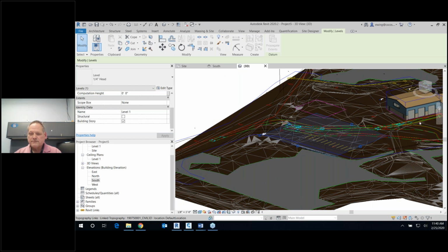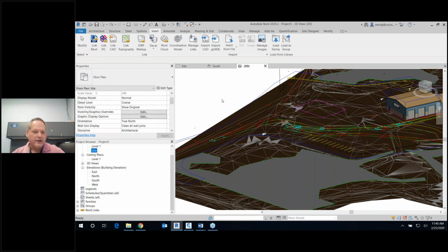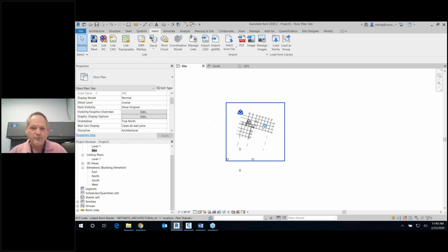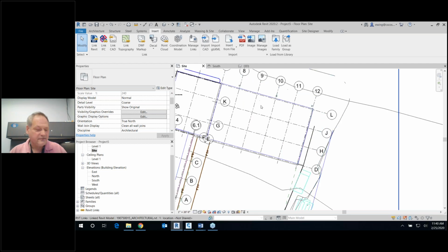Okay, so James is saying, I noticed that you brought all this in, not with Project True North. Does switching it now affect anything you just imported? It won't, because when I was in my site, I aligned the site orientation to True North. But because this is specifically a site model, it doesn't matter. Since we rotated the architectural model into position, that architectural model is what we really wanted to define True North and Project North, right?